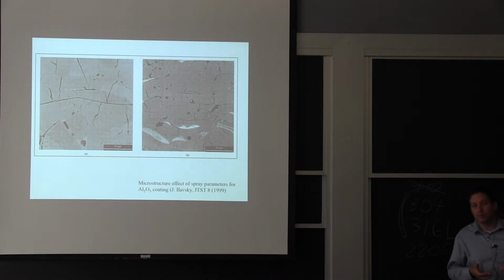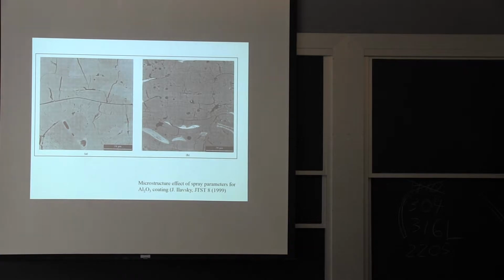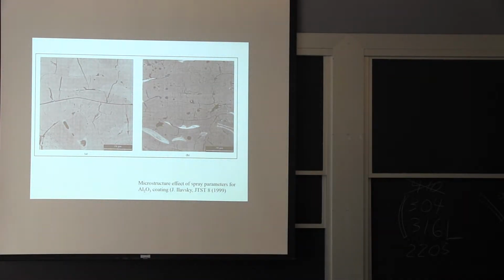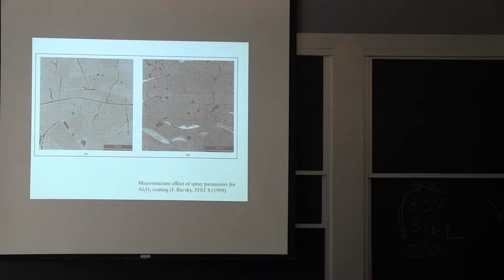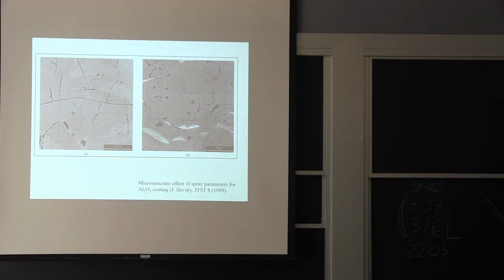So it is used in practice, and there are other ways, of course, to put the ceramics on the blades. One is chemical vapor deposition, and in that process, they also make use of a very columnar structure, columnar grains that will break apart, and during service they actually will open and close a little bit, and that's how you account for your differential thermal expansion.